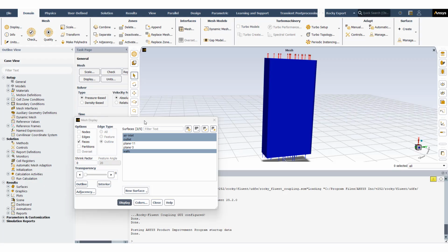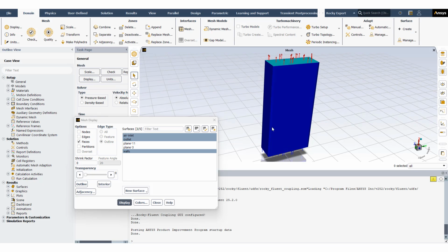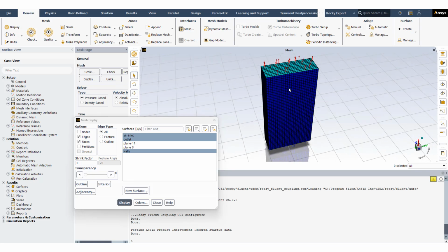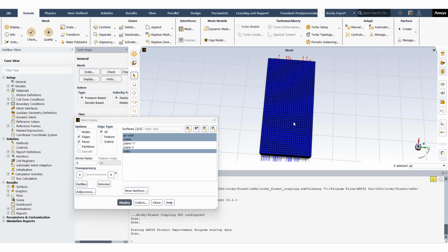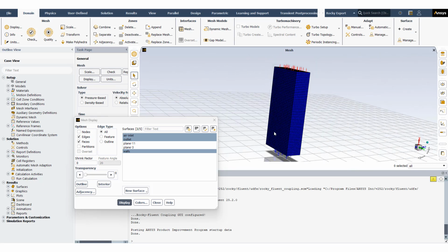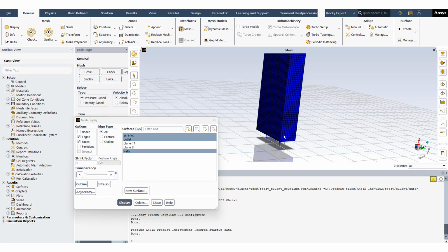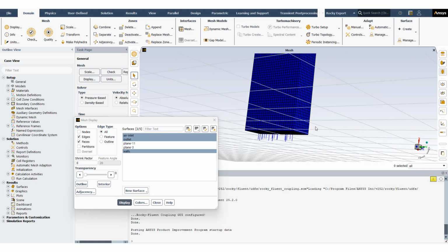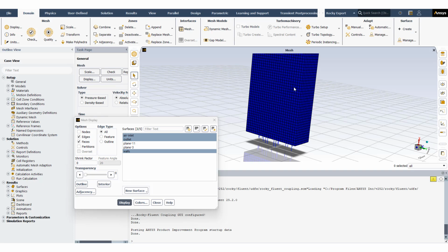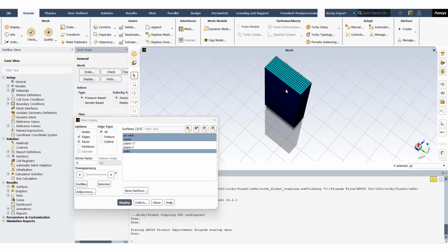Hello, today we will be exploring how to implement a co-combustor, a co-fluidized bed reactor in Rocky and Fluent. So it's a coupled CFD-DEM simulation. Basically I have this fairly simple configuration here, a rectangular fluidized bed with a structured uniform grid mesh developed in Ansys Workbench meshing. So all we have is an inlet with air with some water as well, and an outlet.